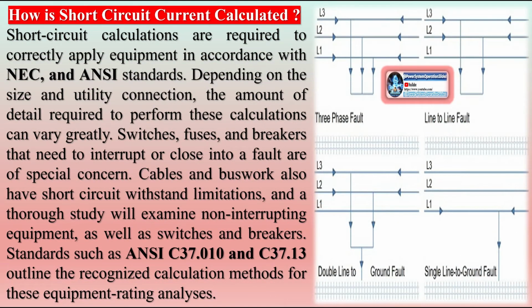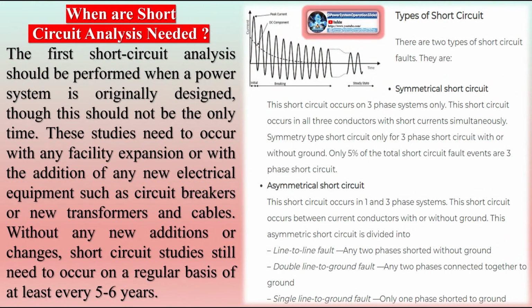As renewable energy sources like wind and solar power become more integrated into the grid, the SCR becomes an important factor to consider. Renewable energy sources are often distributed and can introduce variability and unpredictability into the power system. In such cases, the SCR must be carefully monitored and adjusted to ensure the system remains stable, especially during fault conditions. Wind power plants, for example, often contribute to a lower SCR due to their variable output and the connection of wind turbines to the grid via inverters. This creates a situation where traditional protection schemes may not be sufficient, and special considerations may be required for fault tolerance and protection.